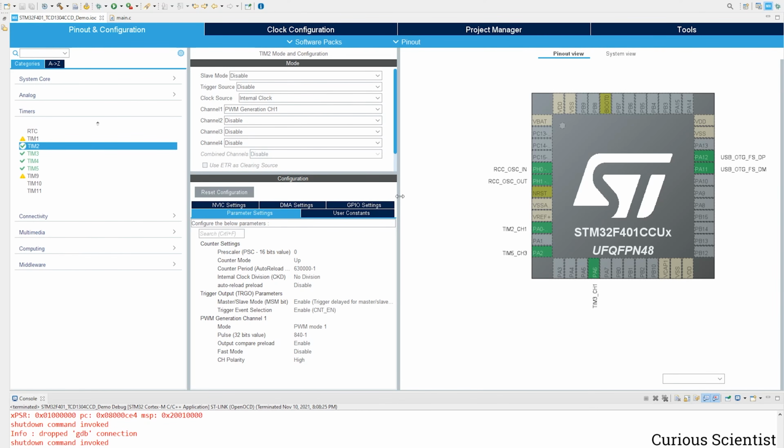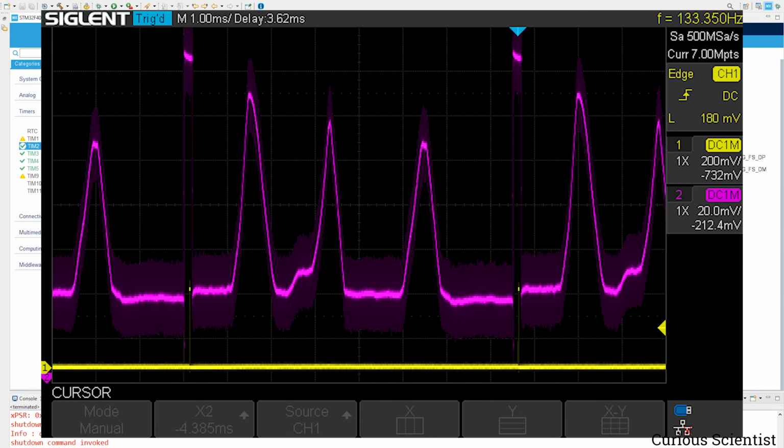So essentially we are done. The CCD is driven, and I put a few wires on top of the CCD, and I can see there are 3 peaks, and you can see the 2 big peaks shown with the arrow. Those are the dummy pixels in the beginning and in the end, and you can see that they coincide with the ICG pulses as well. That is the yellow signal there. So it works extremely well.